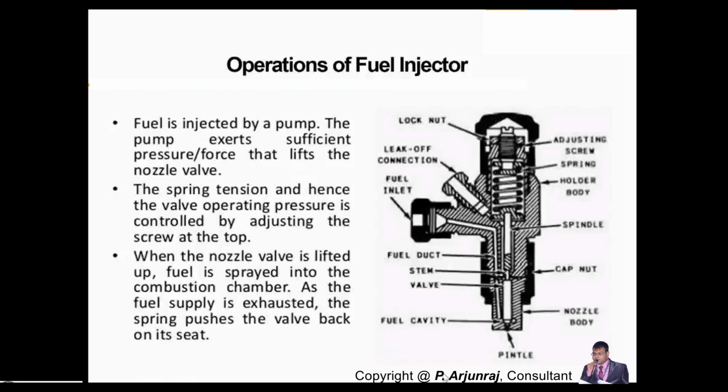You have four types of nozzle: pintle, pintaux, single-hole, and multi-hole. Mostly we go with the pintaux or pintle type because it has high efficiency with respect to atomization, and proper mixing also happens. When you go for a single hole, you have the problem of high injection velocity, which is sometimes very difficult and may not be possible.